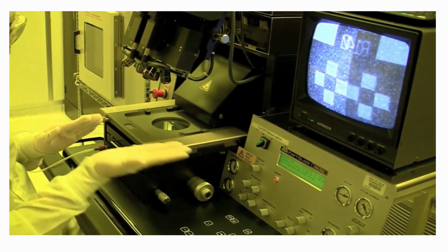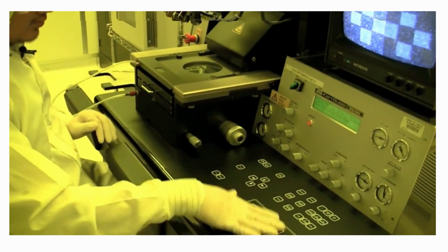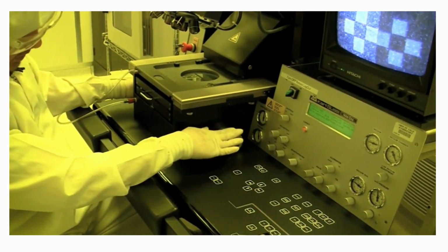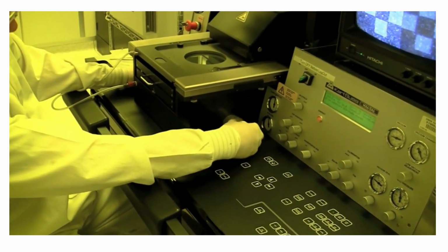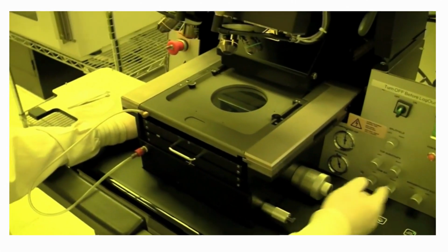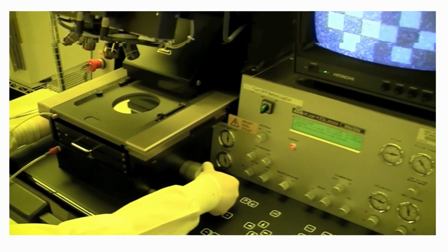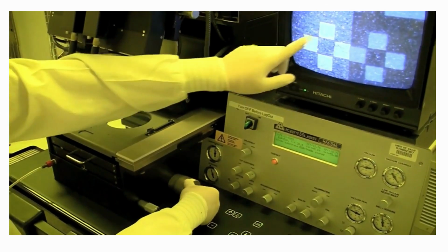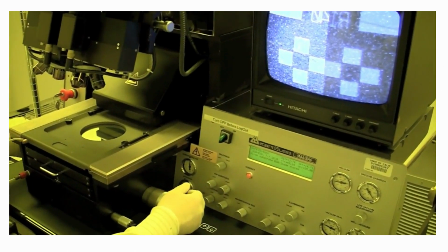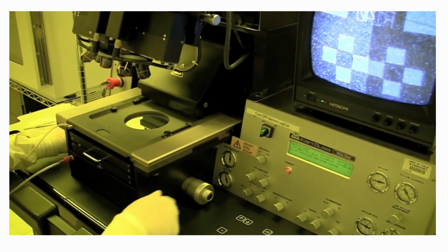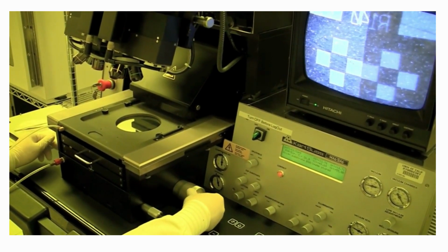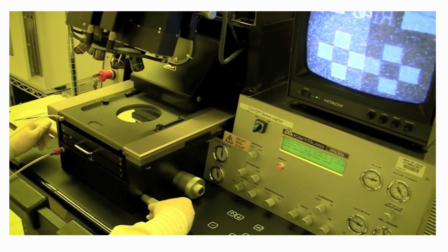So how do you move the wafer? We know that these buttons move the microscope. So how do we move the wafer? It's these knobs right here. This is the Y, the X is on this side, and this is the tilt. So I'll give you an example. I can turn this, and you can see the background, these images, moving. And then you can see this moving. So this is the Y position on the left side, and on the right side is the X knob. And you can adjust the tilt with this too.